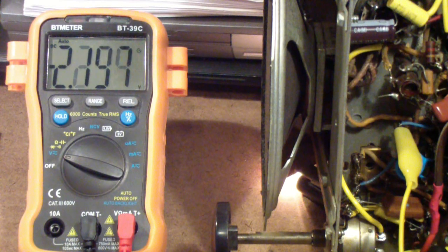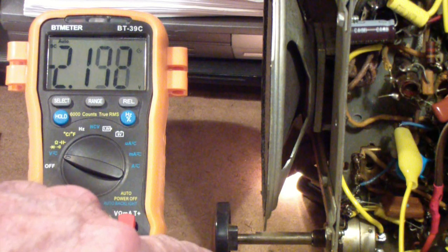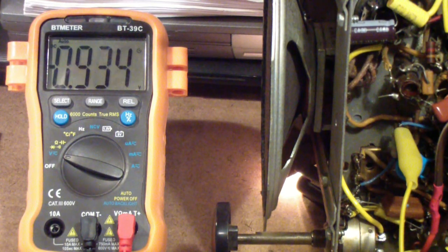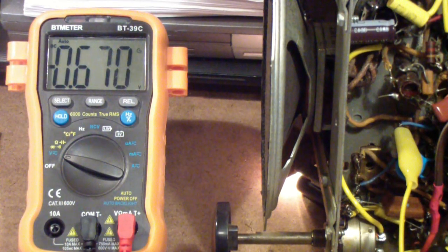And you notice even lower, that it doesn't change with the volume control itself. But now watch what happens when I tune off of the station. You notice it goes down to about minus 0.6 volts. This is the feedback that keeps the volume of the radio relatively constant.